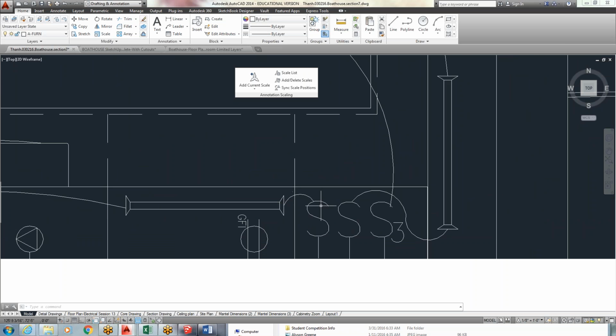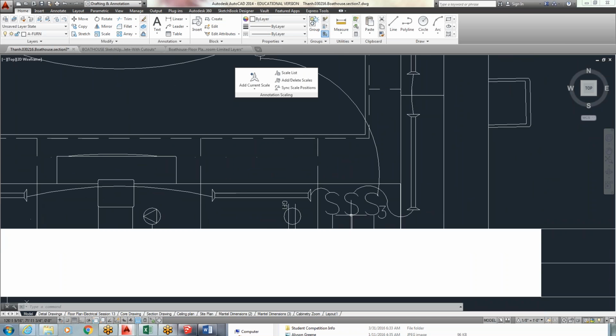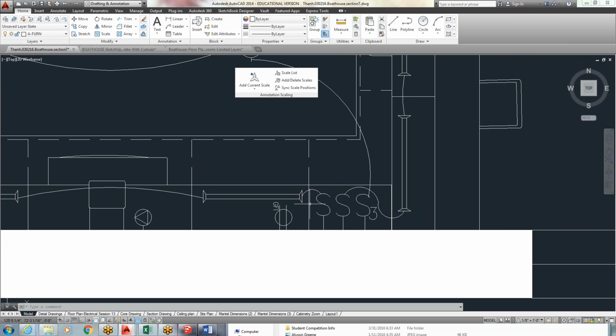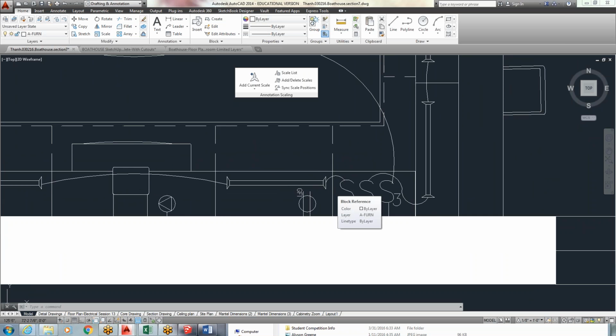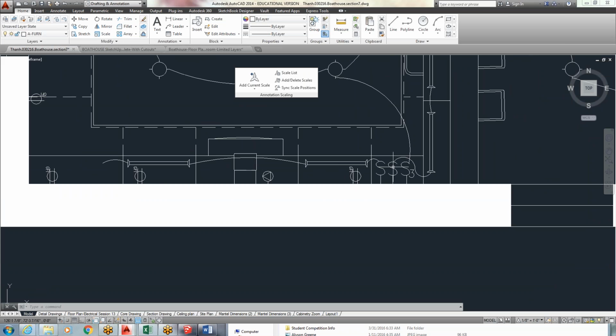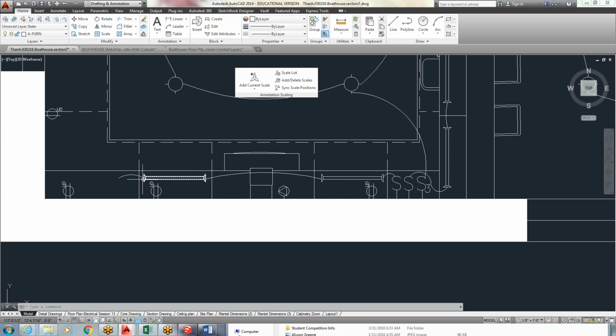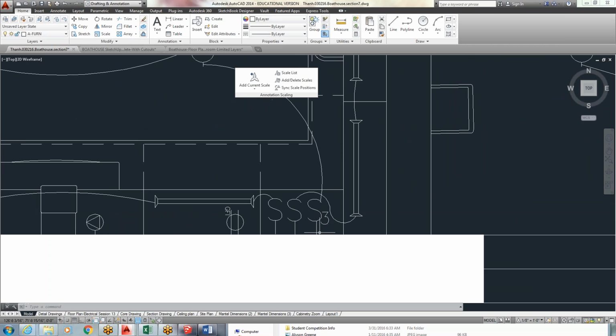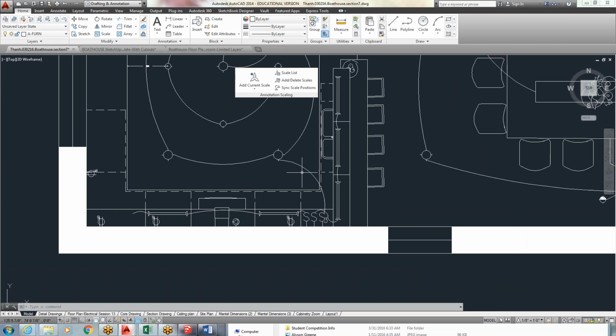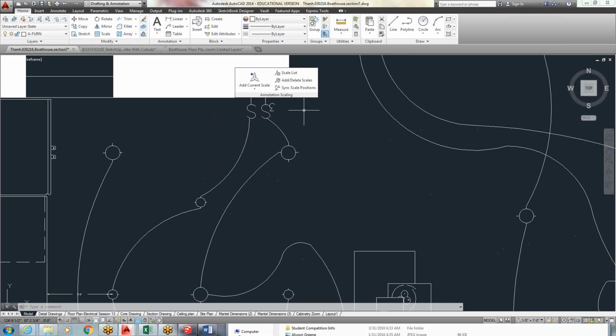Let's talk about switches a little bit. There's single pole switches, and I don't know how each person is familiar with lighting. It's different depending on how far you are in the program, but here's a single switch, and it can support all of my under cabinetry lighting to this side. Then I have another single switch that supports all of this. And here I have an S3, so a three-way switch, which doesn't mean that it has 3 switches on it, and it doesn't mean that it controls 3 things. What it means is it shares controls with the light switch on the other side of the room.